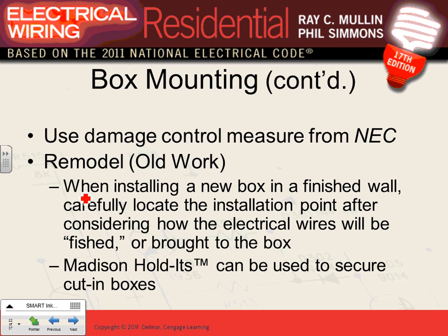When we do remodeling, obviously you guys are not doing design remodeling, but a couple of things for remodeling. You drill a hole. Before you drill a hole and put a box, what would you do, Jeremy? Make sure you can get access to it. The worst thing is you drill a hole for your box without knowing that you can fish the cable into this location. First of all, plan your route, then you put your box.